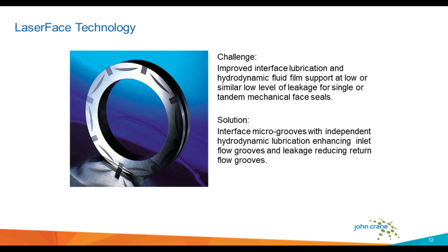So the challenge is improving the interface lubrication and hydrodynamic fluid film support at a low level of leakage for single or tandem mechanical face seals. The solution: interface microgrooves with independent hydrodynamic lubrication, an enhancing inlet groove, and a return flow groove that reduces leakage.